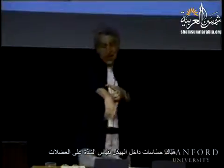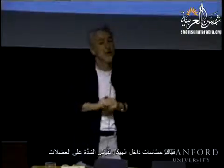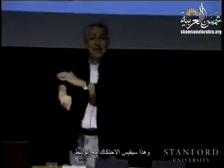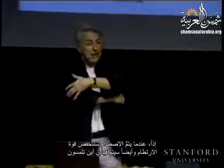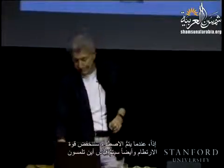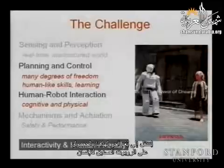Sensors are in the joint or at the extremity or both? Well, there are sensors inside the structure to measure tension on the muscles, but also we have sensors distributed on the skin outside, and that will measure contact with the environment. So when you hit first, you dampen, so you reduce the impact force, and also you measure where you are touching.